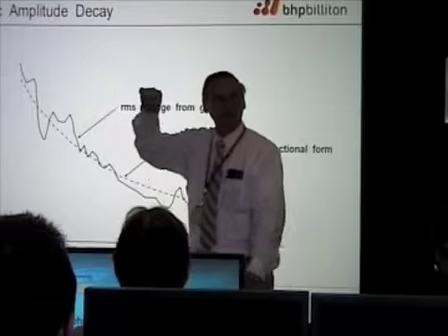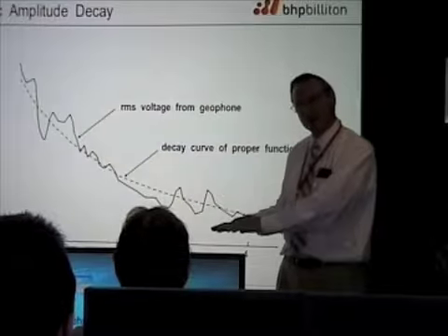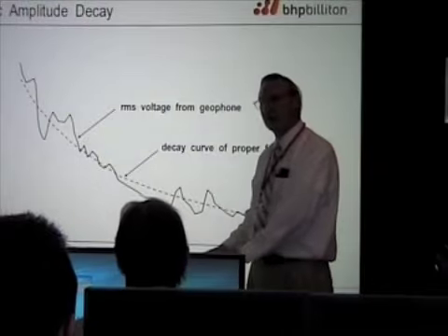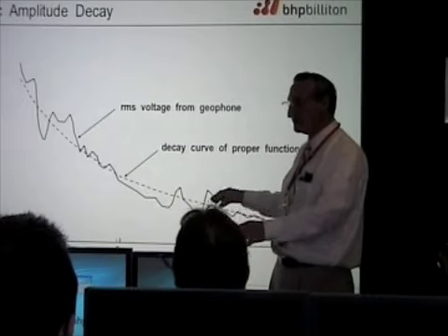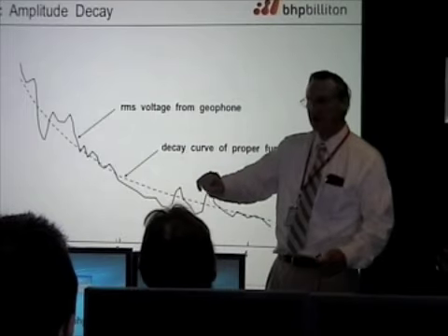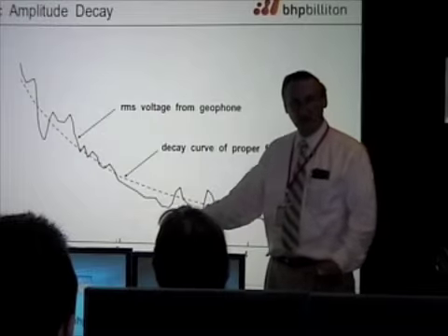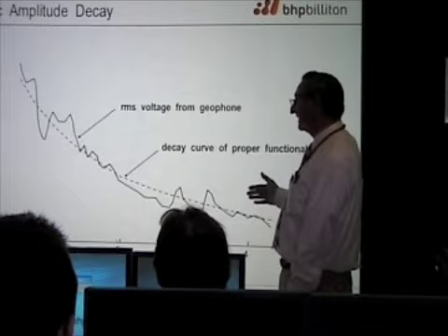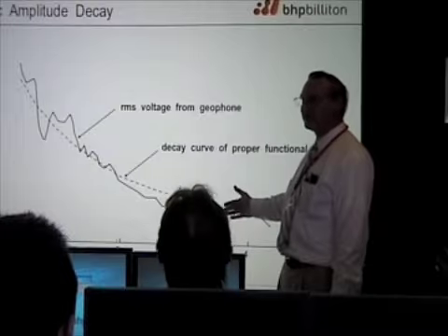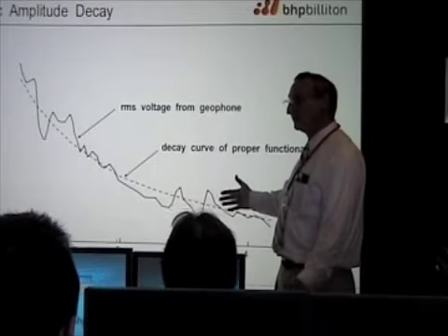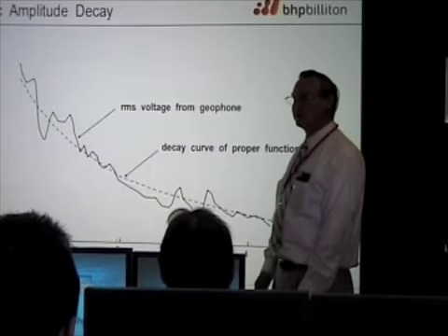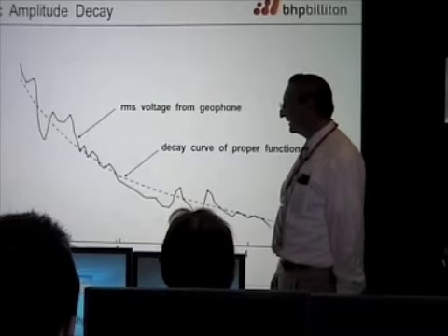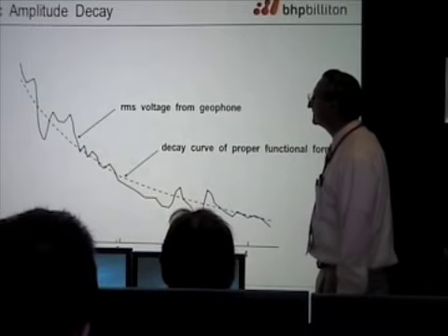That Falklands data that Mike just showed you looked very nice. You saw those nice reflector events at the top. If you got down deeper, as you get down deeper in any record you look at, it's going to get hashier and hashier. You're not going to see nice coherent events so easily that bop along and you can easily correlate it back. And why is that? Because the signal is getting weaker and weaker. Eventually it drops into the background noise of the seismic amplifier if you go that far.